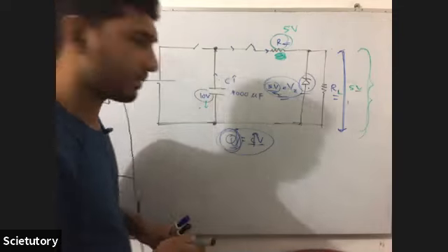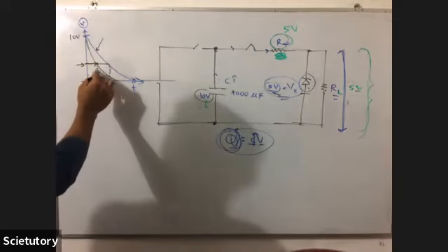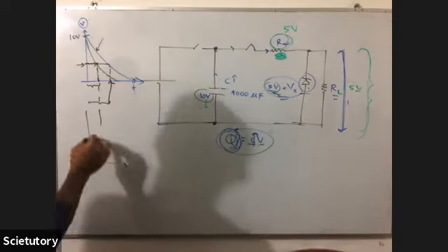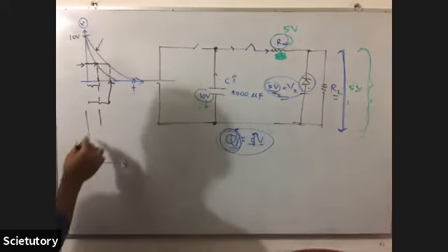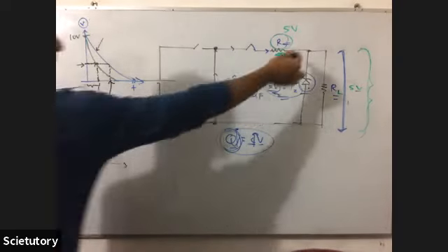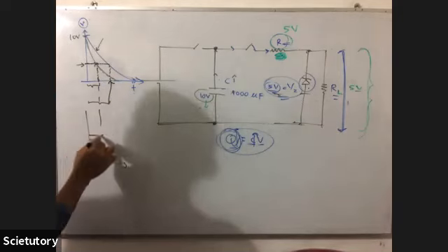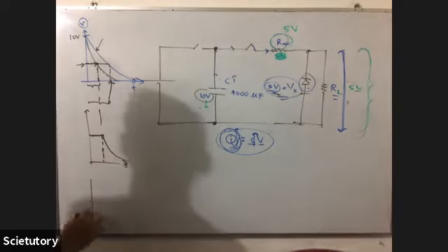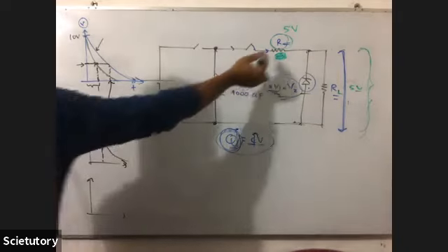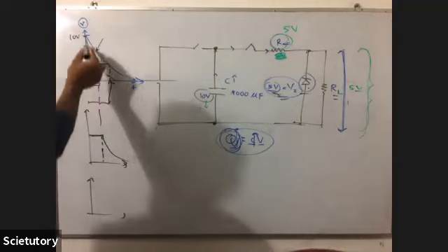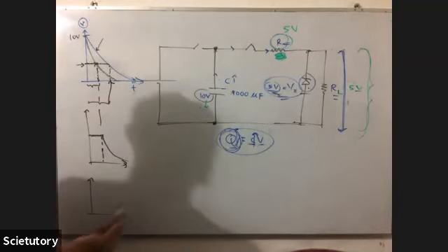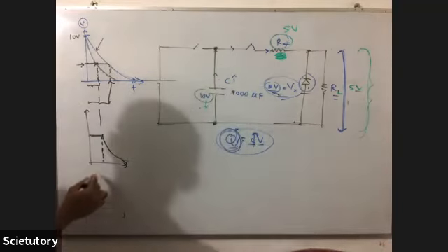You understand that? So up to this point, you don't see a voltage drop across this part of the circuit. So this part of the circuit, if you draw the voltage difference, for some time it remains as 5 and then it falls. But when you draw the graph for this resistor, it was always experiencing a voltage drop.